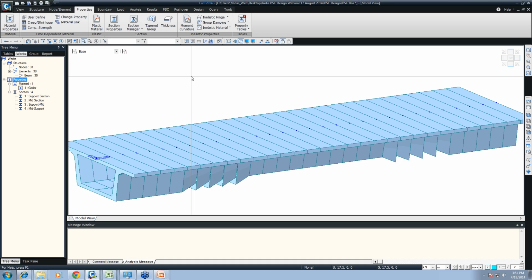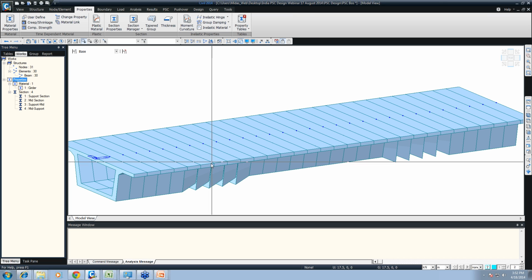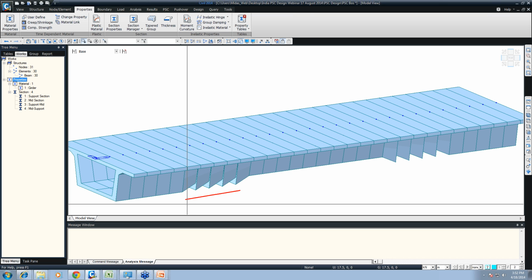Once we go to the solid view, you will find that all the section properties are given, but you are finding some rough adjustments here, right? This is plausible because Midas will identify each section as a separate section, and each of these sections will have its own I and its own J. Whatever ith and jth property tapering we did will taper from its own ith section property to its own jth section property. So we need to generate some tapering properties.